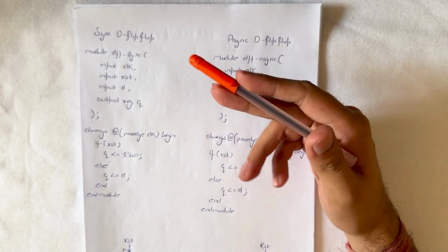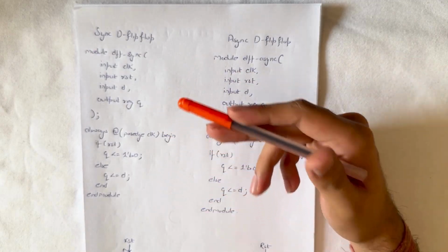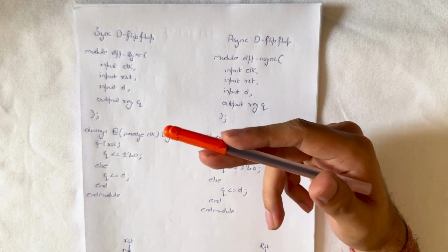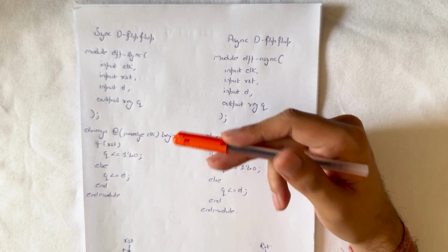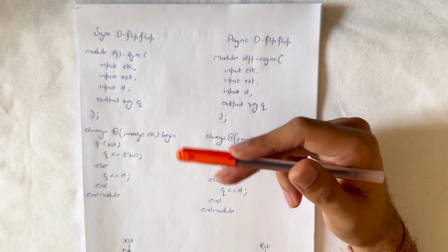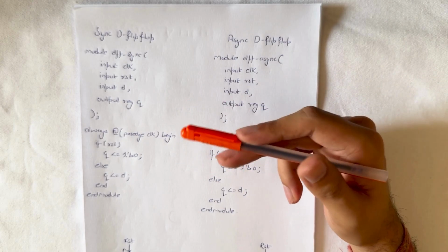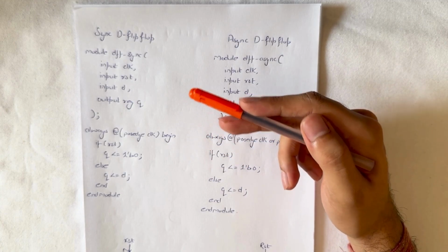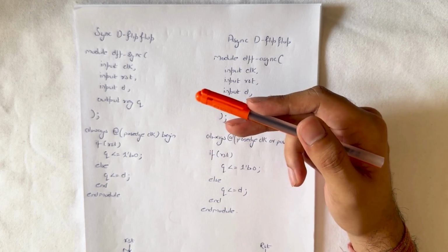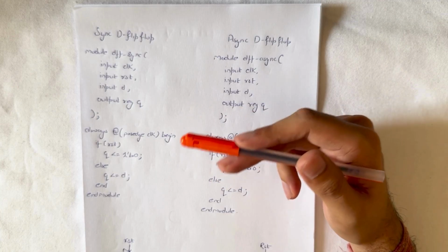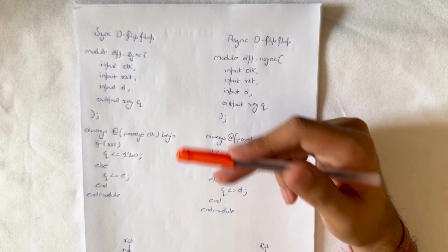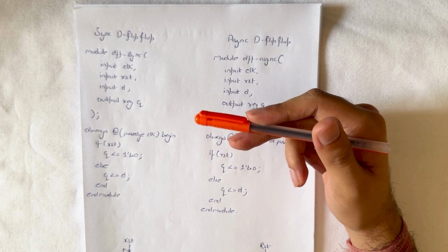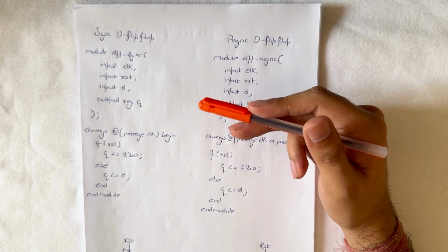After writing the RTL code, the next step in the design flow is synthesis. During synthesis, the tool converts the Verilog RTL code into gate-level hardware. For a D flip-flop design, the synthesis tool typically maps the RTL into a standard cell flip-flop from the technology library. In the synthesis report, you will see things like number of flip-flops used, number of combinational logic cells, area utilization, timing information.